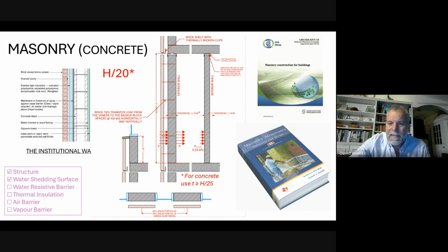To the right of that is an interior wall. So an interior wall, why do we worry about an interior wall? We have interior wind load. You probably never felt interior wind load, or not that you were aware of anyway. But we get interior wind load. The simple example is you're in a room on the perimeter of the building and the window's open. When the wind blows, you get an influx of air, you get an outflux of air, and the pressure in that room changes relative to the adjacent room. And that's interior wind load.